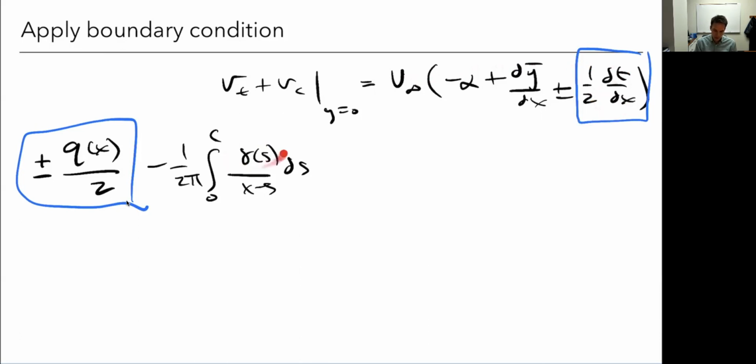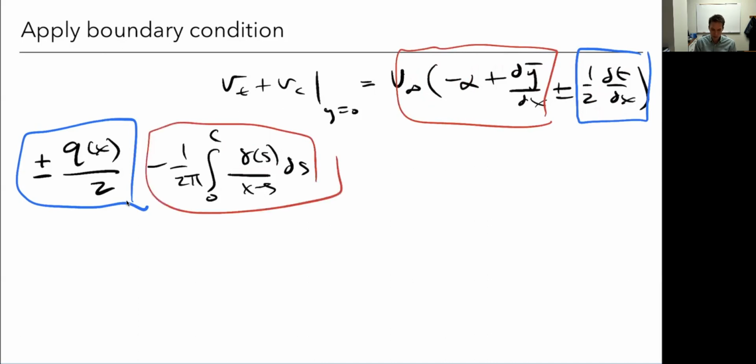Whereas the vortices, we're going to equate with the lift part, so camber and angle of attack. So this stuff here, we're going to equate to this part here. Okay, so if we do that, notice this plus and minus is the same as this plus or minus, so the signs are going to be the same. And there's a divided by 2 on both sides. And remember, I need to put that V infinity over. So if I do all that in one step, I get Q of X equals V infinity times dt dx.